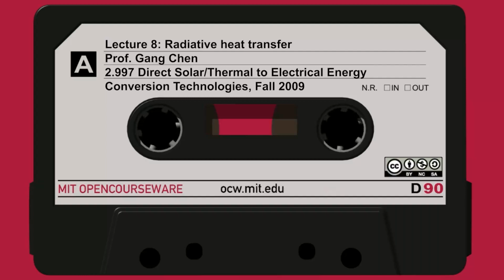The absorptivity of the surface is a function of wavelength lambda. And then also the emission, it will re-radiate, right? So for absorption, if I do directional, I know Kirchhoff's law tells me absorption equals emission per wavelength like this. At least if I say directional-wise, it's the same. So it's all diffuse, you can imagine that. Okay, so when I do this,